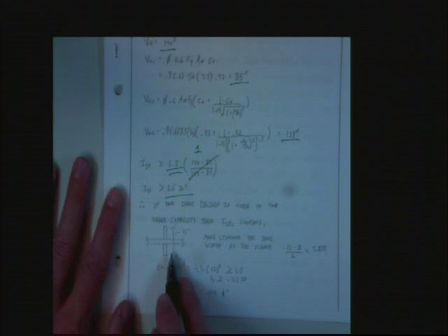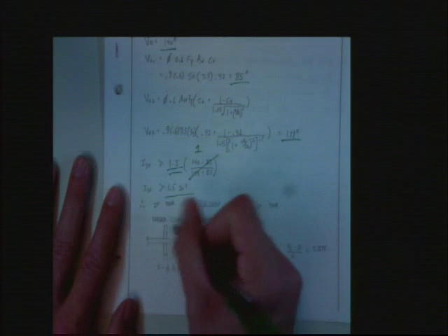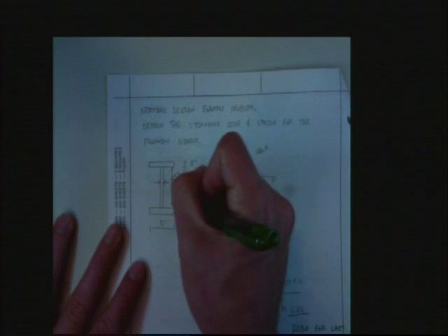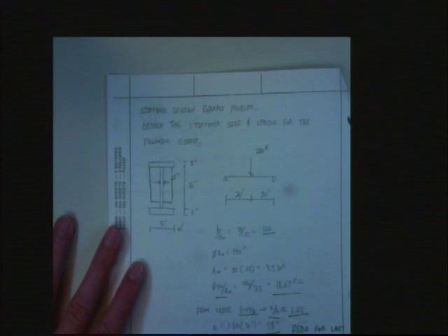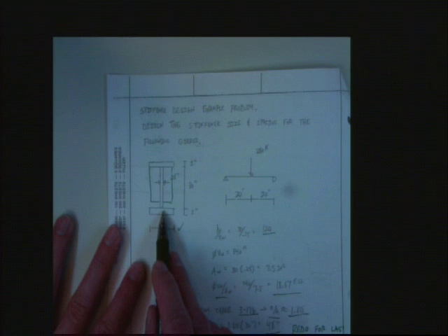This is a joke. I'm just showing this just in case you needed to do this. It's very, very common to make your stiffener the same width as your flange. Extremely common to do that. I'd argue if you didn't do that, people would wonder why. You'd get calls: why didn't you make it the same width?